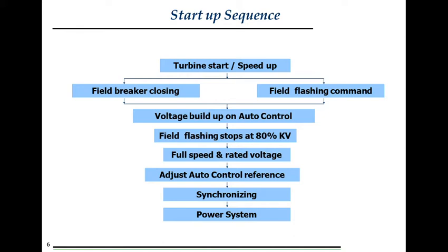When a generator is rotated by an external force, the rotor bars cut the magnetic fluxes generated by the residual magnetism property. By cutting those fluxes, a small amount of EMF is induced in the armature. This is basically Faraday's law of electromagnetic induction, which we have already discussed.